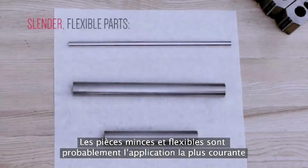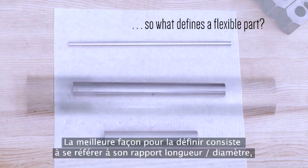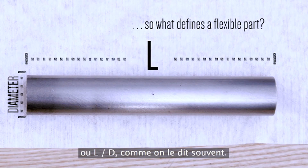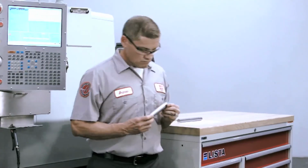Slender, flexible parts are probably the most common application where tailstock support is required. So what defines a slender, flexible part? The most common way is to refer to its length to diameter ratio, or L to D as it's often referred to. But let's be more specific. It really isn't enough just to look at the L to D ratio of the part by itself.